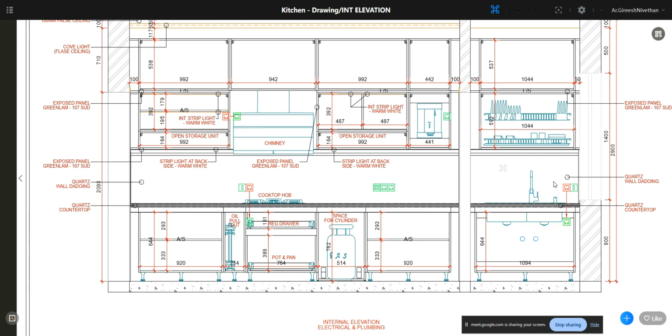Can you see the annotations? And this is an internal elevation. It is a common practice to mention if there is a shift in the electrical points compared to your civil versus your design. In those cases, it is a practice to mention that in your internal elevation, right? So that way, I added a socket here which was moved to this part. Can you see?